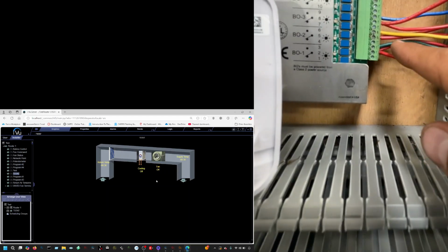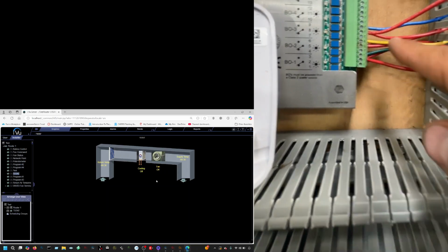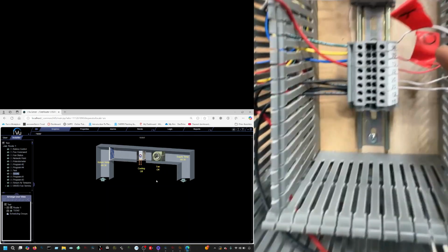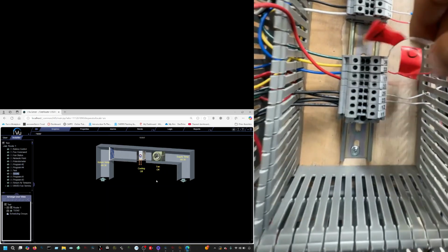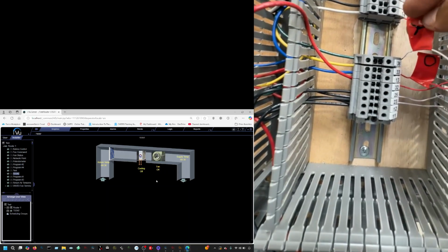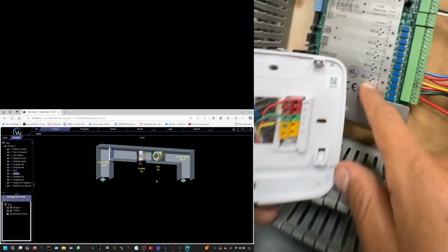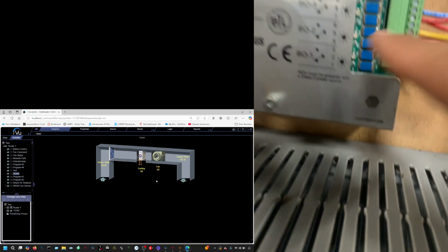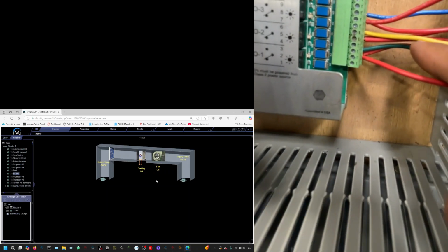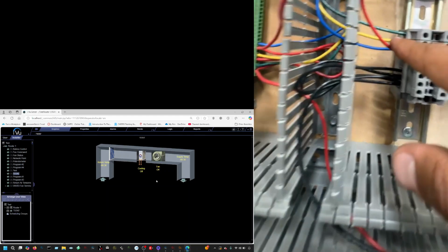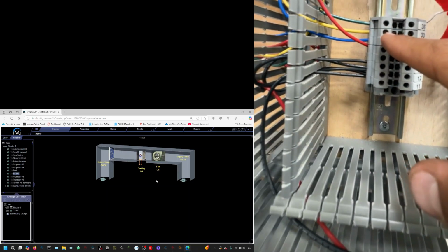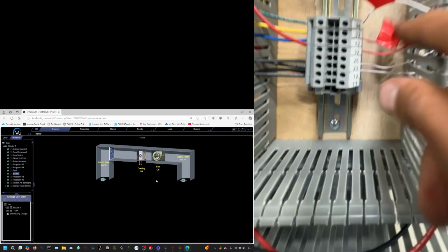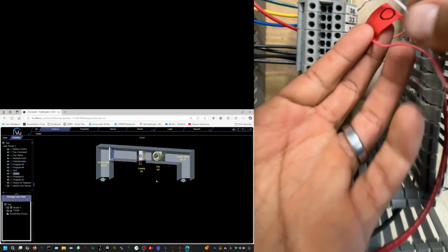And if you follow this green wire that's on 3, it goes to this wire here, which I taped, and it's Y. If you go to binary output 2, on number 6, I have this yellow wire coming out, going to this right here, the second spacer slot, and then I have this red wire that says "O."